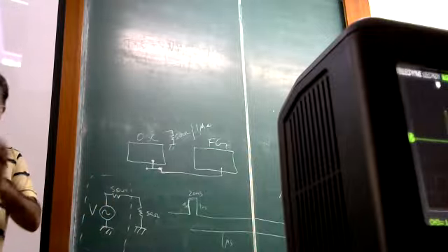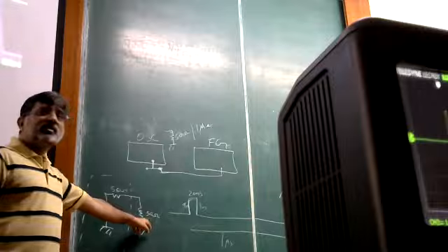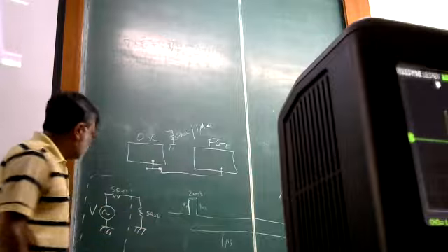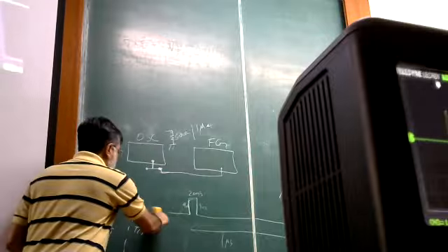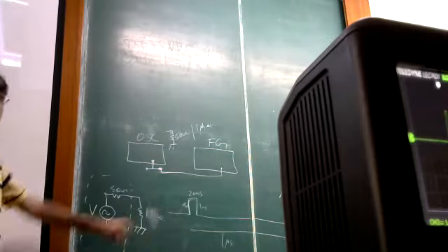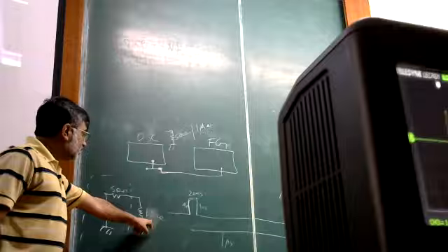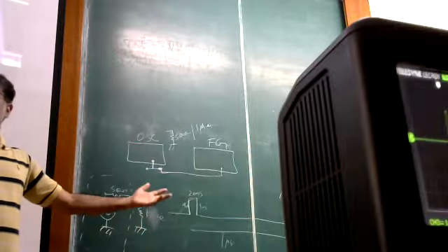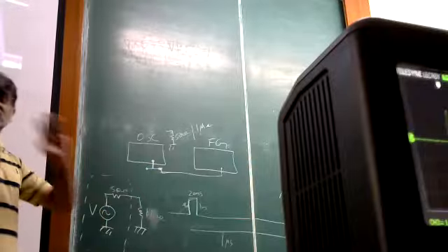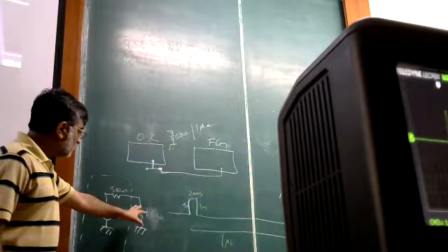So these instruments try to make it convenient for you that if you're working in an all 50 ohm system, it will give you the voltage or the power that is dropped across the load. However, instead of connecting a 50 ohm load, if I connect an oscilloscope whose input impedance is 1 mega ohm, then you're actually no longer getting this division, right? So it's 1 million over 1 million plus 50, which is basically 1. So you will measure the true voltage, which is actually here. And this can cause serious mistakes. And this is something which happens in the labs all the time. So this is just a little digression to mention this.